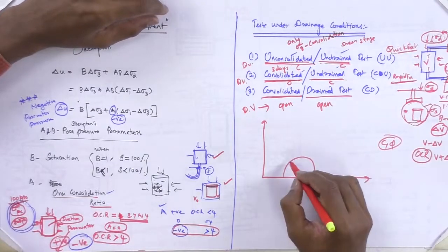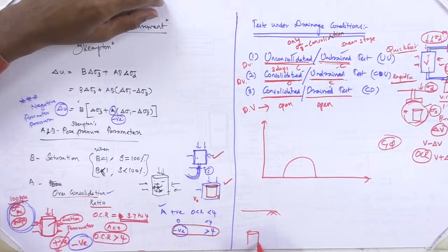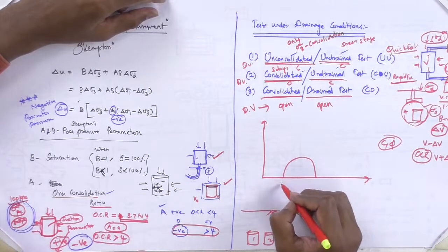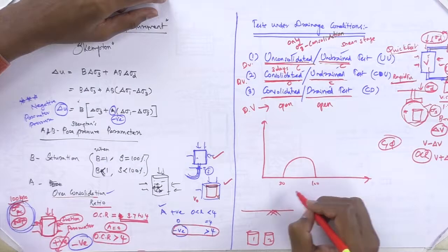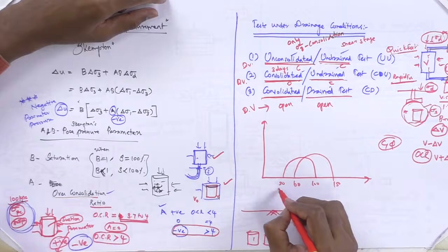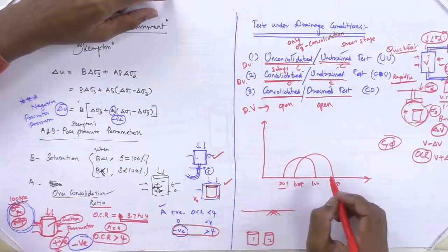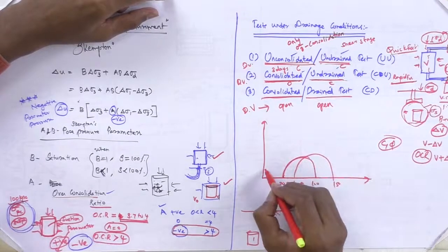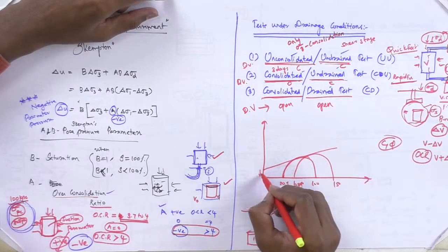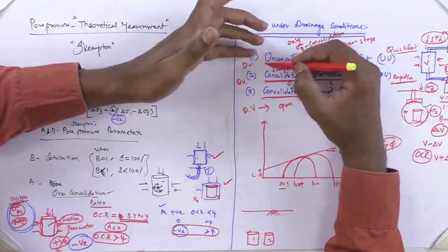So you can draw a circle for the one sample collected. We need to collect two samples, sample 1 and sample 2, representing the same structure, undisturbed sample. For sample 1, we get 30 kPa and 100 kPa. For sample 2, you get different values, 60 and 150. This can be increased by just adjusting the knob. The constant confining pressure can be increased. Once you get these two circles, you can get the C value as well as the phi value, if you have done this under different drainage conditions.